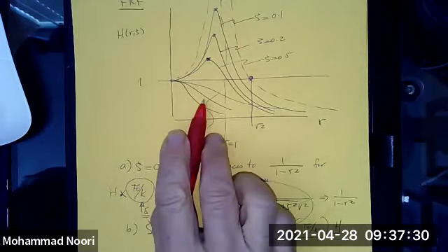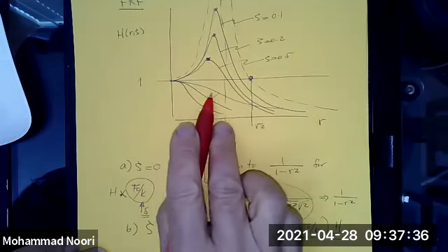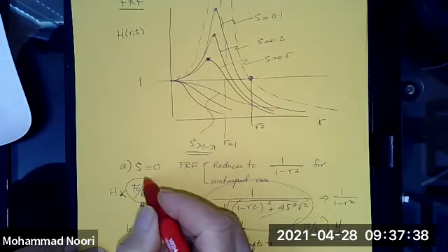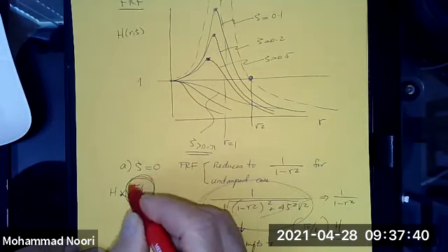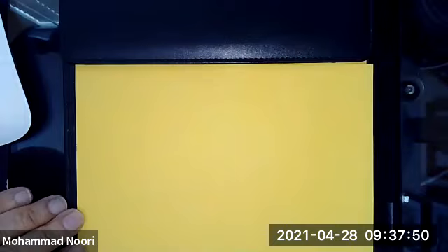So when the damping is greater than 0.7, or 70%, the dynamic displacement is always less than the corresponding static displacement. Now let's see why it is so.